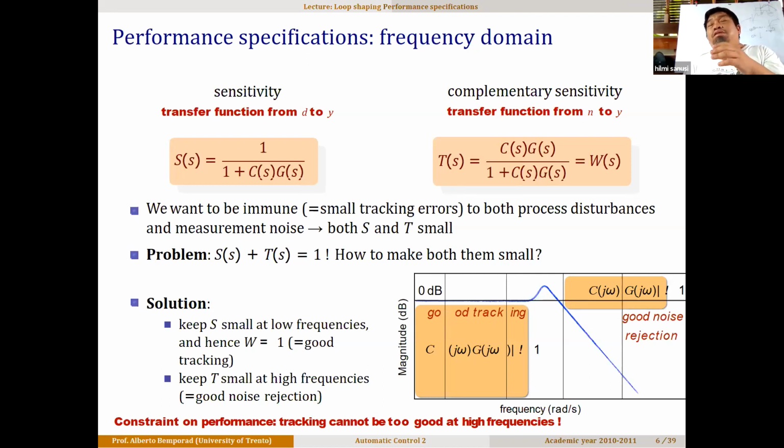Maybe the accuracy is better when it's closer. When it tracks far away, at a distance of 10 km, maybe the error is about 100 meters. When it's already close, the error is 1 or 2 meters. So this is the accuracy. Then the aeroplane's speed is based on Doppler. Sometimes the aeroplane's movement will also change its Doppler reflection. So this will give you the measurement noise.